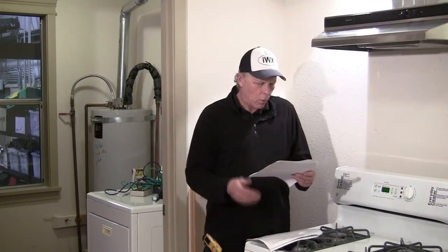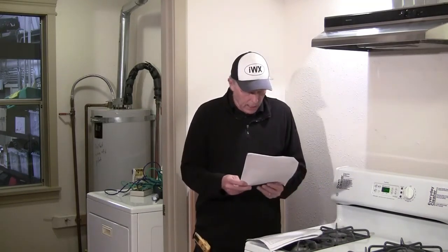We're on line 10. This is where the candidate must apply the correct action level according to the current version of ANSI BPI 1200 for the CO in the oven. We ended up with 240 parts per million as measured. I'm going to look up what the threshold is for ovens on my BPI sheet, and it has it listed at 225 parts per million as measured.